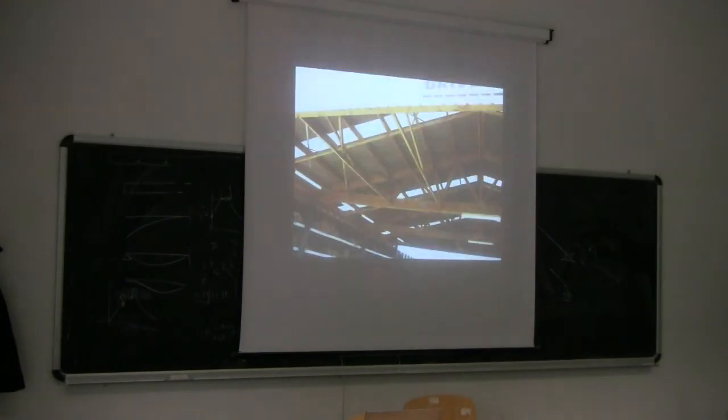This is a photo from outside, and here you can see the main trusses. So those are the main trusses, and then those are the secondary trusses, the ones that run perpendicular to the plane. And the function of which, as you can see, is to provide some lateral restraint in order to make sure that those trusses cannot buckle out of plane.